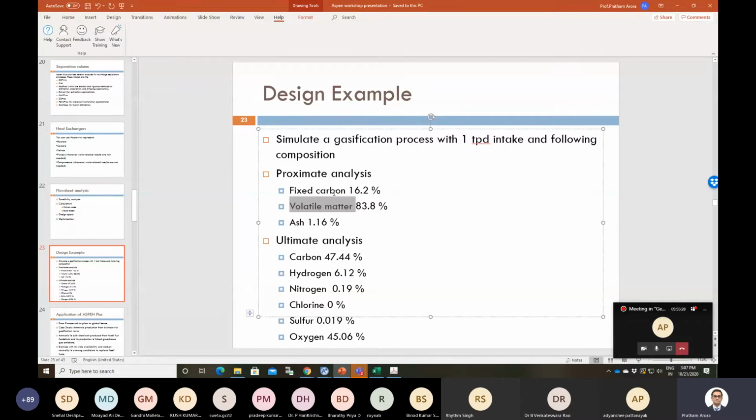The carbon that is left behind is fixed carbon that won't go away if you keep on heating the biomass in the absence of air. If you combust it, this fixed carbon would also go away, and what is left behind is the ash, the gray thing that is left behind in any bonfire. That's nothing but elements like silica, potassium or calcium, which form the ash, which should be in the range of 1 to 2% in any conventional wood.